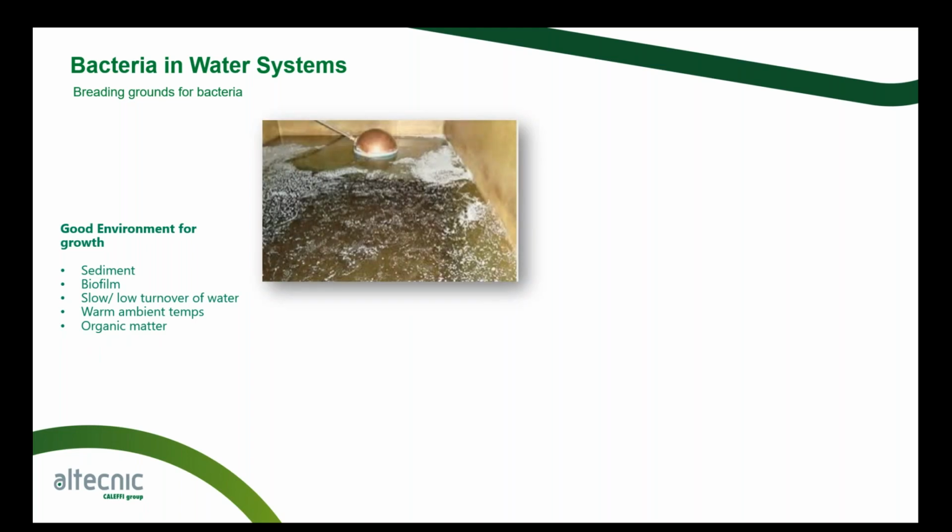Now, these are some examples here of what we're looking at. So this is a cold water storage tank. You can see that the condition of that water is not great at all. And the fact that water hasn't been turned over for a vast amount of time, as you can tell by the state of it, that tank probably is no longer required because it's just not been used. It's not getting the turnover of water. But a risk assessment carried out by a competent person would be able to identify this as a risk within the system and point out that tank should probably be removed, or the way it's used certainly be reviewed.